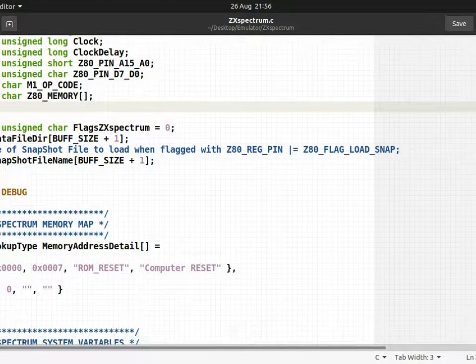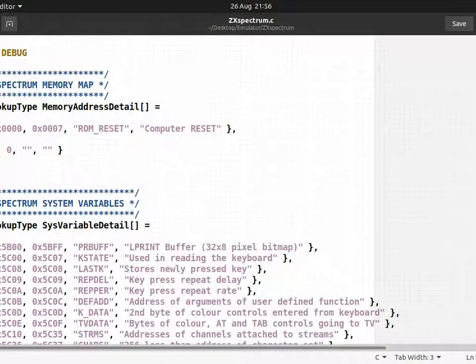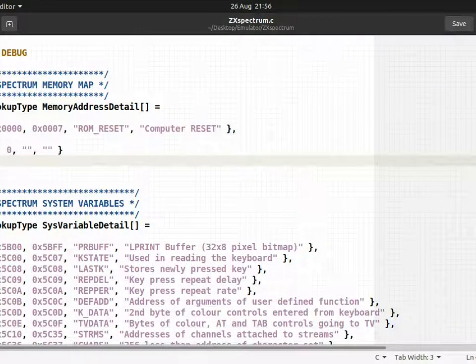At the top, like I said in the previous videos for the Z80 and ZX81, these are just lookup values, which are actually on the Spectrum. I haven't really filled these in yet, because this is to help me with debugging. As I step through the code, it can tell me from these comments on each line of the assembly code what the Spectrum's actually doing. When I work something out, I put it in here, and then it comes up automatically in the assembly listing.